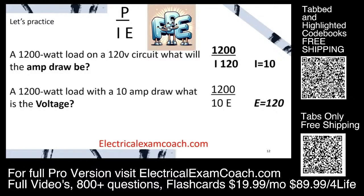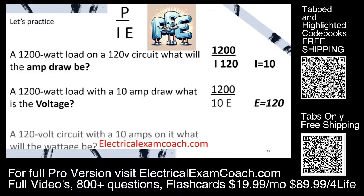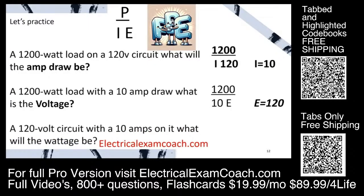So we divide and we get 120. And if we have a 120 volt circuit with 10 amps on it, what will the wattage be? That's right, all we have to do is multiply it out. And when we multiply 10 by 120, that equals 1200 watts.